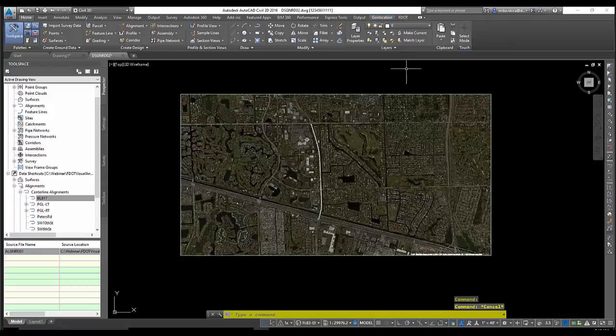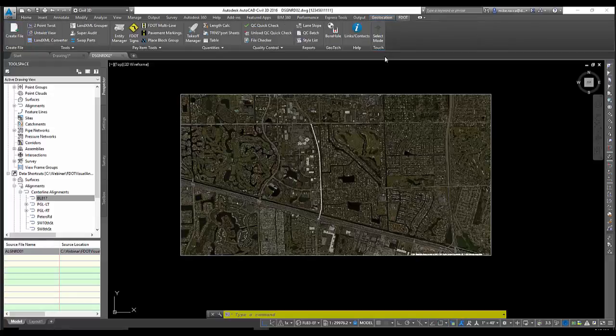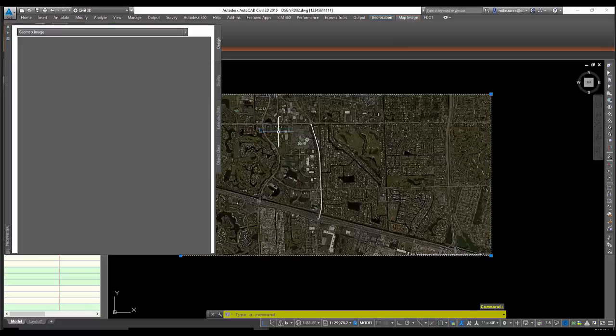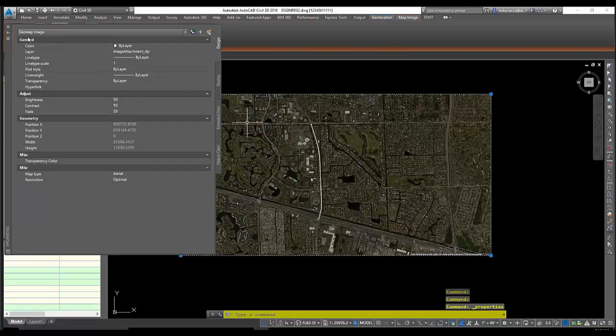And like I was saying before, this is now an image that you can print. Before, you could only view these images in a drawing; if you went to print them, it would have a big watermark that would go across them. That is no longer the case. These images are now part of the file. If you pick the image and go into Properties, Civil 3D recognizes this image as a GeoMap image.